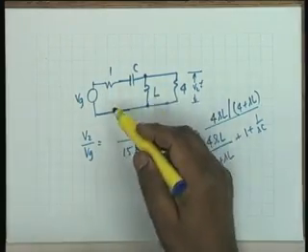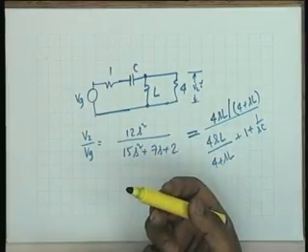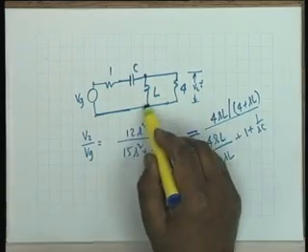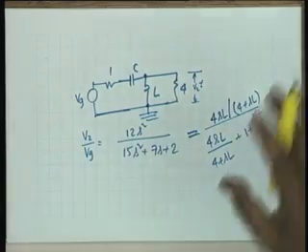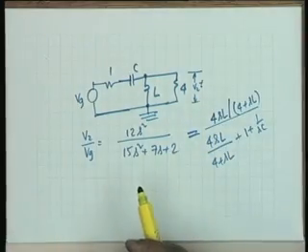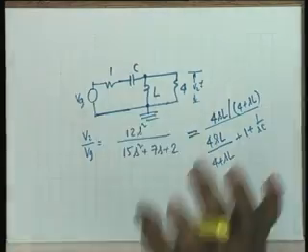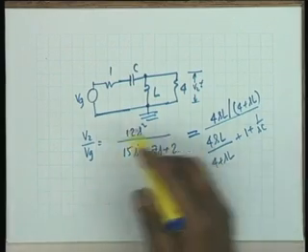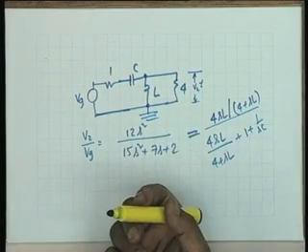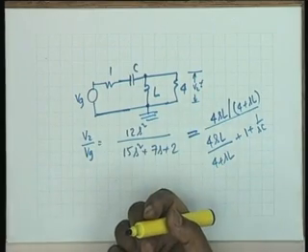Well, in this loop, it doesn't matter where that resistance is put. This is the most favored type of circuit in which the input and output have a common ground. That solves many of the electromagnetic interference problems. So this is the type of network that we usually prefer. That's why we have chosen this.